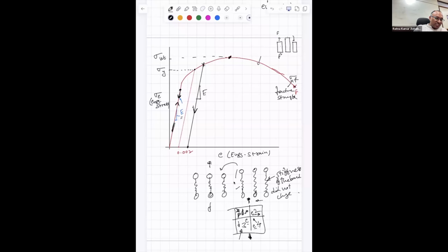So now when I have removed the load, the stress is zero, but is the strain zero? No, sir. Although I have removed the external load, the stress has become zero, but the strain is still there. That is what we call plastic strain. This is what we have as permanent deformation. The material did not come back to the point O. The material has come back to, say, point P, which has some residual strain. That is what we call plastic deformation or plastic strain.